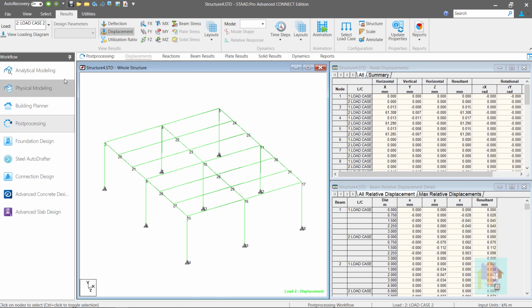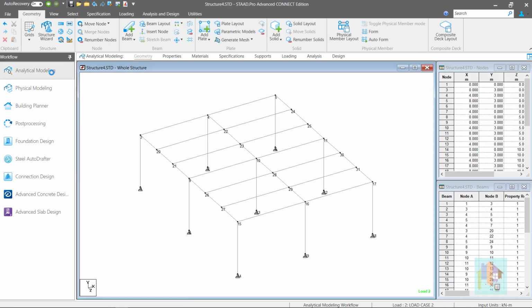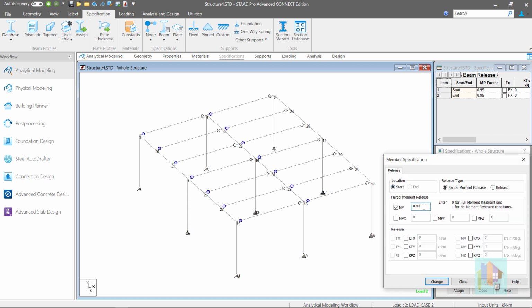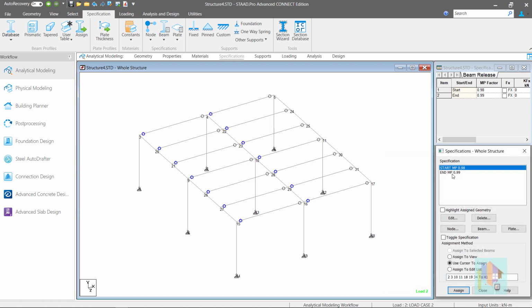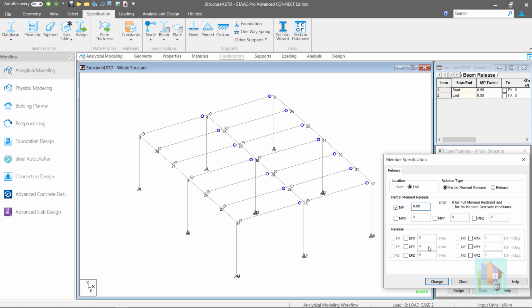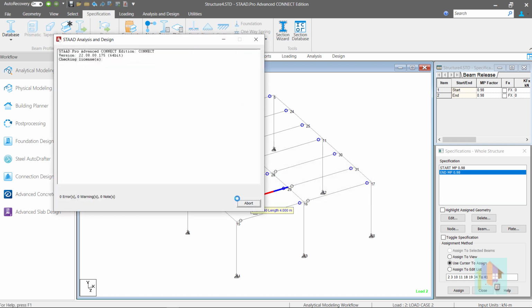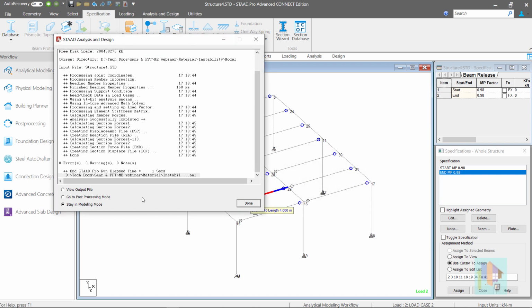We can further modify the stiffness value to reduce the deflection in x direction. This will obviously increase the end moment, and we need to consider that during design. This time, I want to increase the rotational stiffness from 1% to 2%. So MP is now 0.98 at both ends of the member. Reanalyze the model. We know the structure is stable, so no warning is reported.